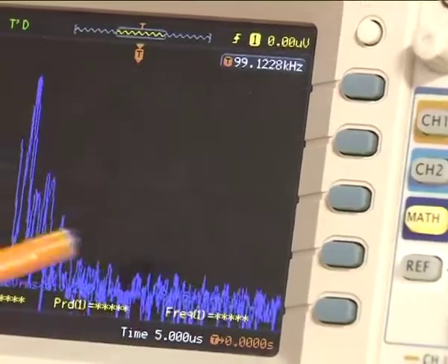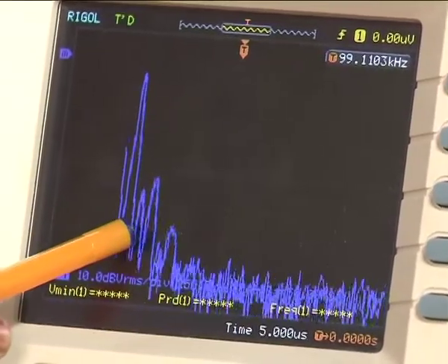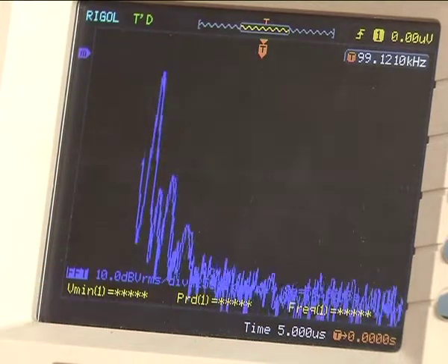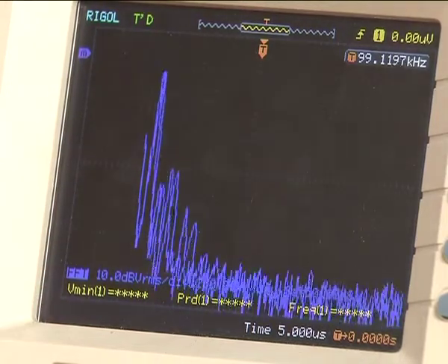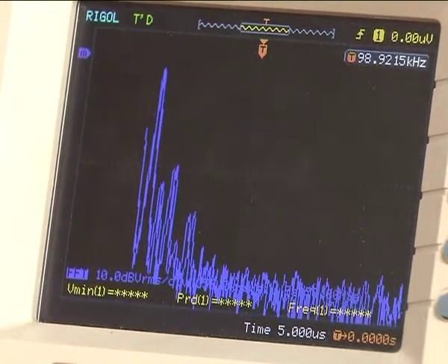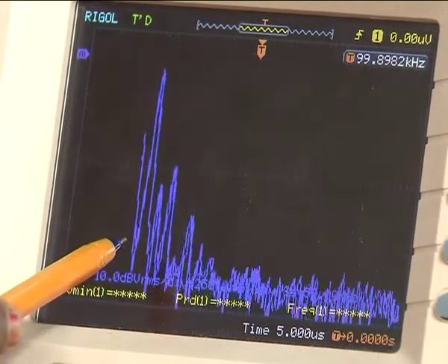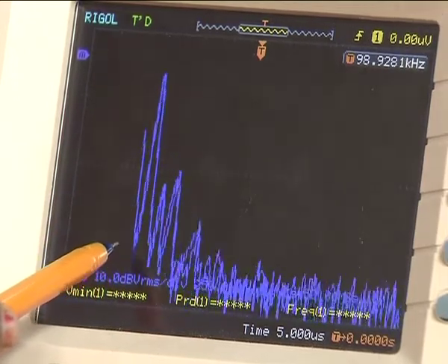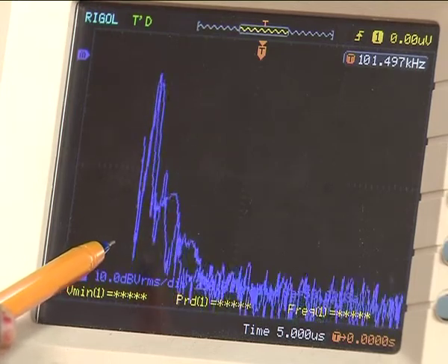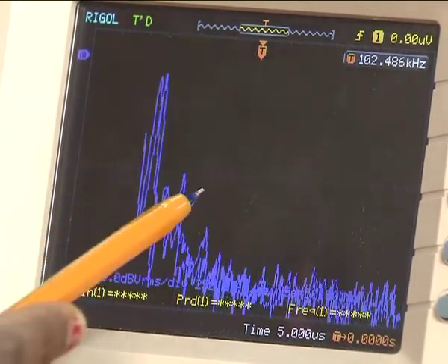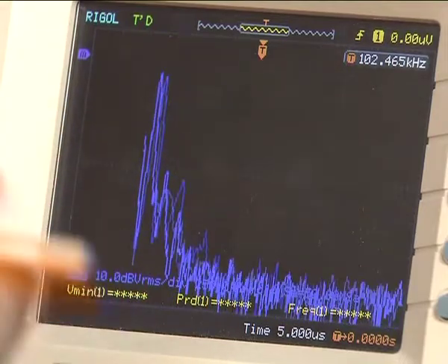You can also verify that the bandwidth occupied will change with respect to the amplitude of the input signal. As I increase the amplitude, the bandwidth changes. So, by varying the amplitude of the input signal, we are going to measure 2 or 3 bandwidths and write it as an observation.